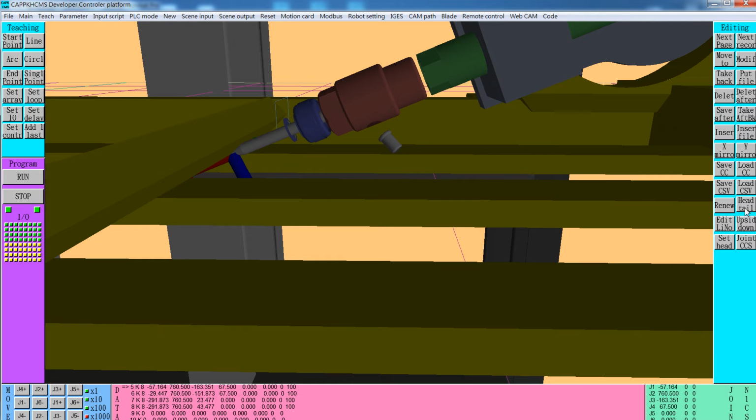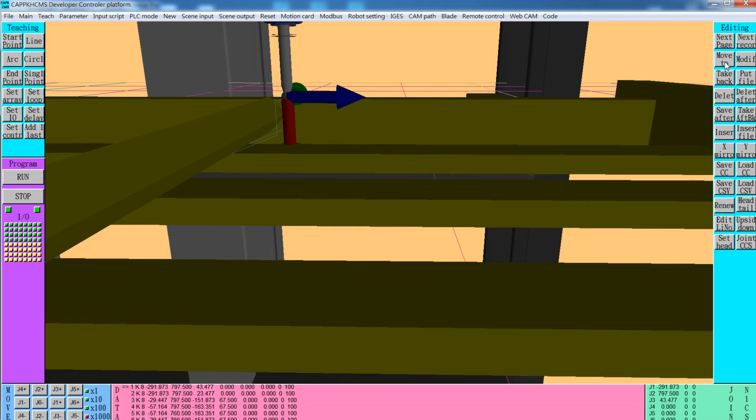So we see visually whether the script in the data field runs okay or not. It's very hard to tell from the digital value. It's better to see the system provides the tool path simulation to see the tool cutting in 3D simulation.